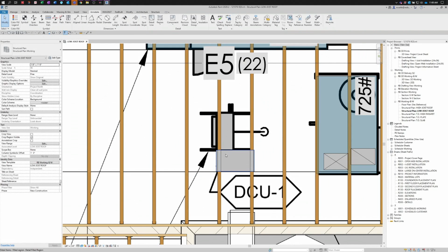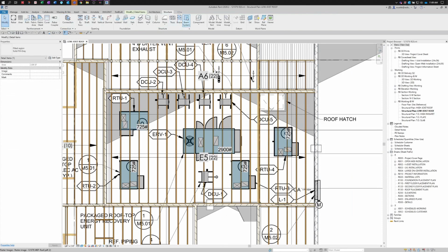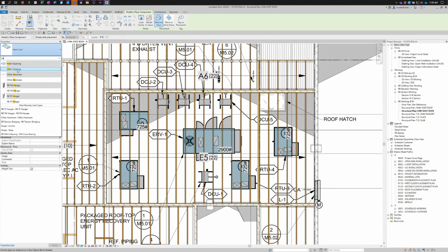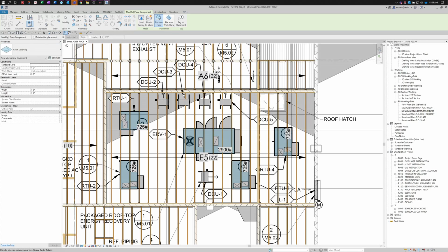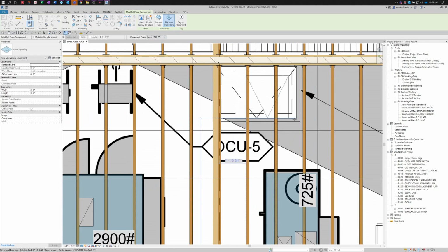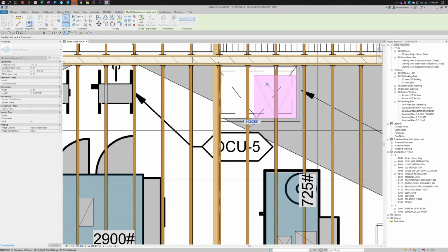And finish rotating and aligning these. The last thing I need to add is the roof hatch family. Let's go back to the structure component, the type selector, find in the hatch opening. Selecting placement work plane for the E5. Using the spacebar to rotate it to help match the hatch. After placing it, I want to select it and use the shape handles to stretch it to size.